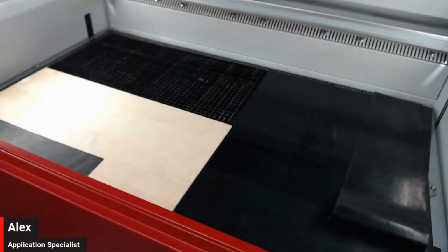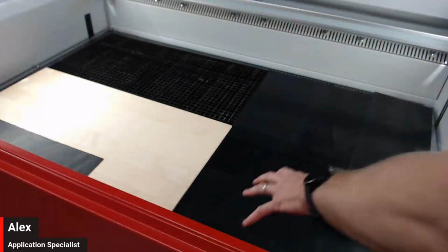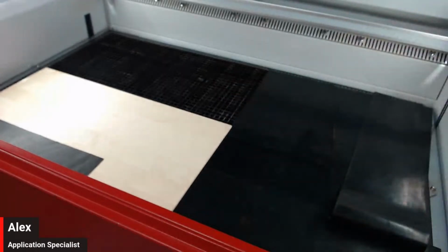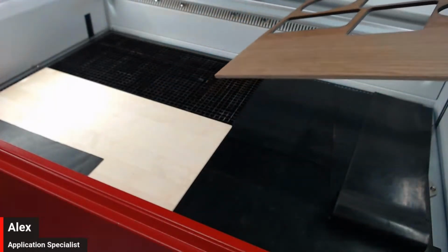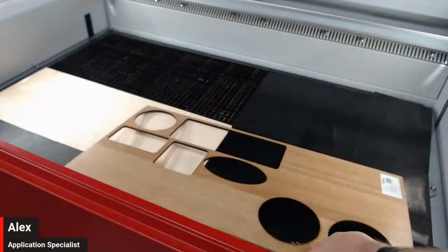A lot of people overlook extraction as part of their laser setup, which then results in additional flaming, more burning, and less clean cuts. It also makes it more difficult to process thicker material. So by blocking it off, the extraction is going to be focused around the area where we want to process, which is always a good thing to do.